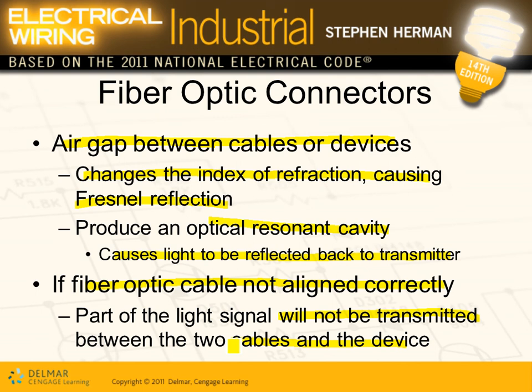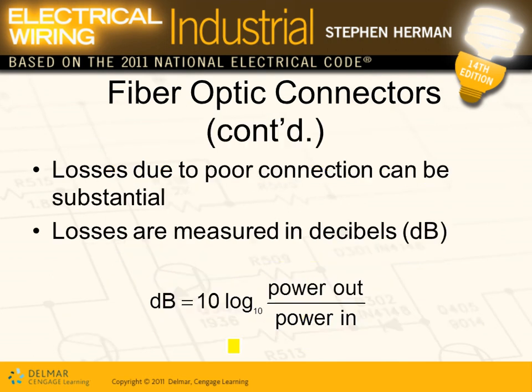Slow and lose some data. Karen, any comments, any questions about termination? It is very important. Aligning the cables and terminating them properly, polishing them, and using the proper tools to cut the cables as you terminate them, because you can't have one single cable from here to Texas, can you? It has to be multiple cables fused together, attached together. So you have to do termination.